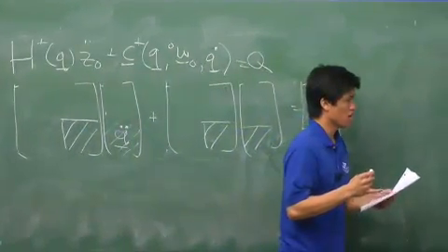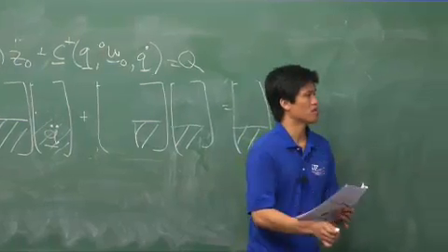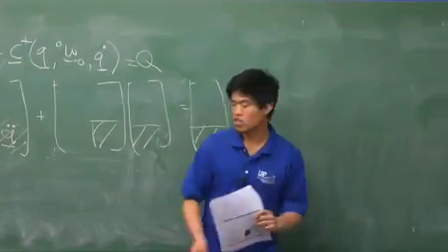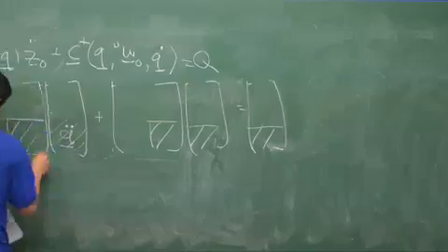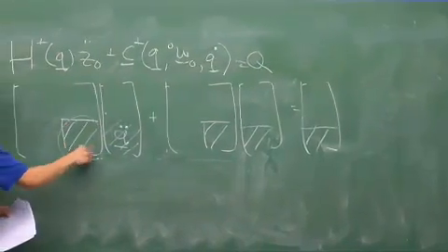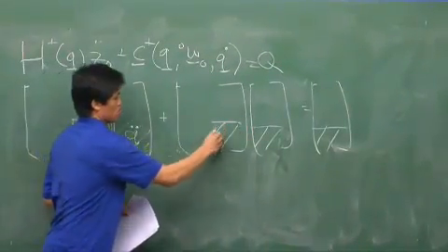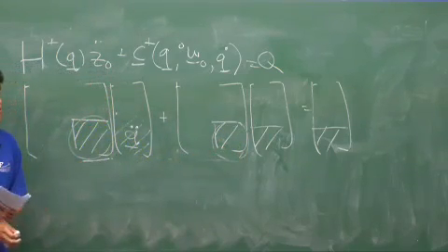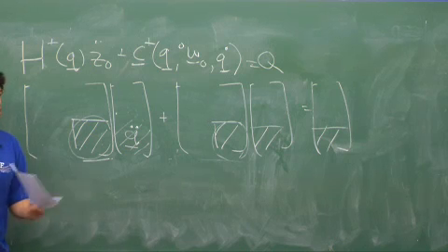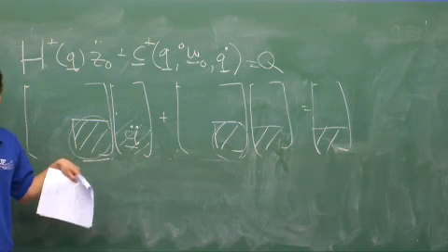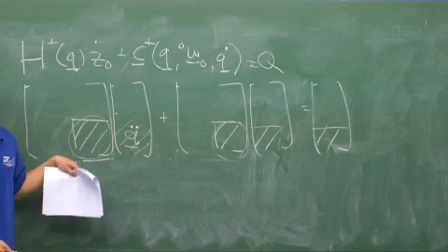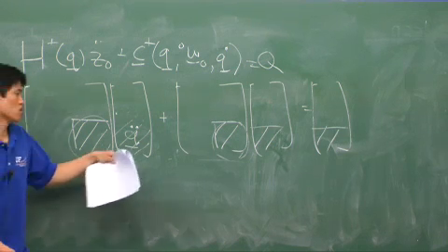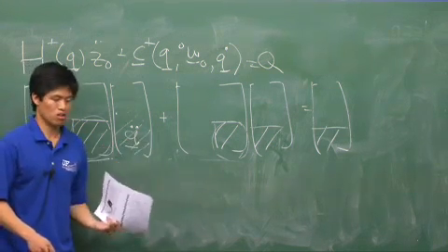The other important property is that there is a relationship between this portion of the inertia tensor and this portion of the centripetal Coriolis matrix, and it's the skew symmetry property for a fixed-based robotic arm manipulator, which is an Euler-Lagrange system.